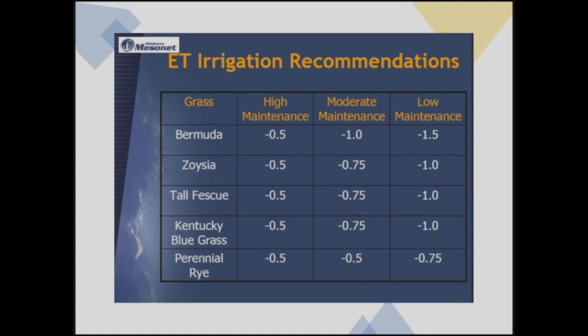So ET irrigation can get really complicated, or it can be really simple. And so you just need to find out where it works for you. But what we want to get to with ET irrigation is not replacing the water when we don't need to. So he said 60%, which is a pretty good guideline, 60 to 70% depending on how used your field is for sure, and what soil type, right?